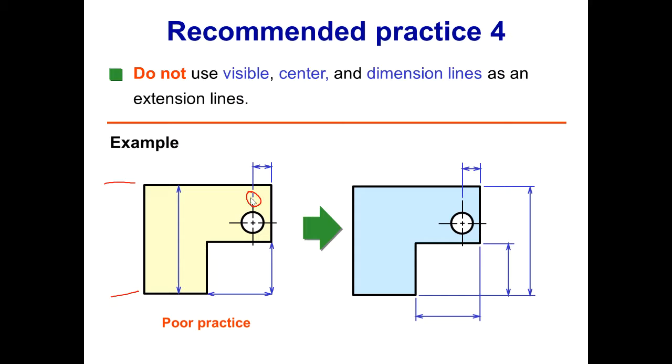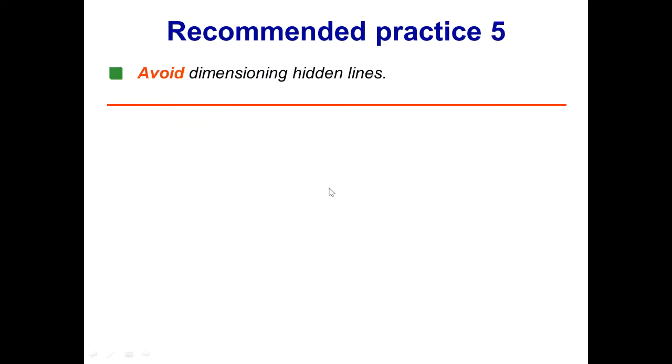It's basically they are using the center line as an extension line. So these are the wrong practices. These are the right practices. Basically they are using the extension lines and the dimension lines for giving the dimension, and now they are using basically a dimension line and an extension line to give the dimension instead of extending the center line.